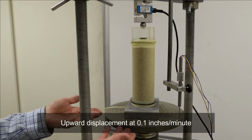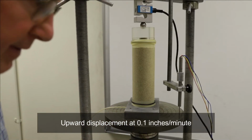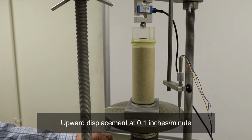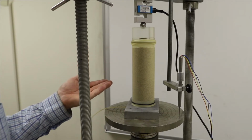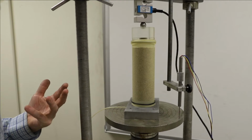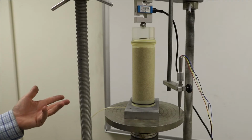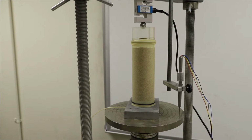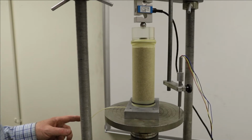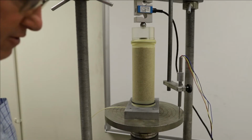So the table is going to move up at a rate of 0.1 inches per minute, which is relatively quick for a soil strength test, but that's good for what we want. We don't have any water in the pores that need to drain out of the specimen or need to equilibrate in terms of pressure or anything like that. In fact, we're not even measuring the vacuum with the computer. We just need to note what that is. Yeah, it's still about a half an atmosphere. I'll calculate what it is and put it on the data sheet based on the gauge we have. So let's get it started.